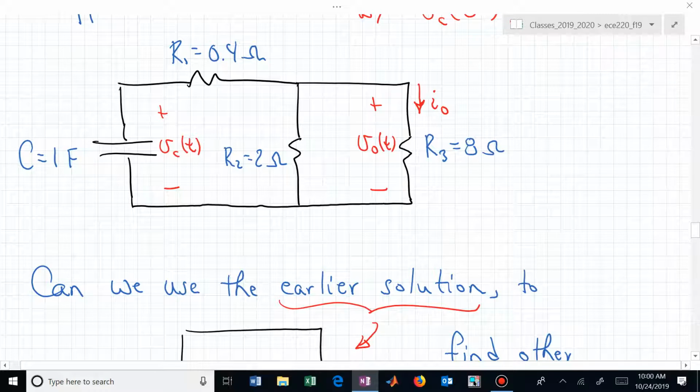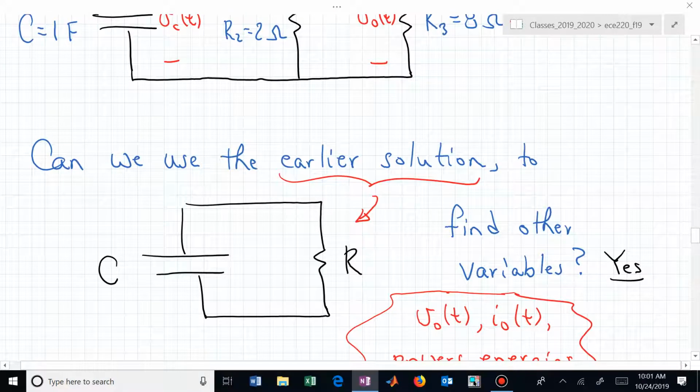Your terminals of the capacitor, or let's say terminal A and terminal B, you want to go, okay, what's the Thevenin resistance between those two terminals? What's the resistance between terminals A, B, where A and B are on either side of the capacitor, and now we're looking into that circuit from the left to the right, and we want to know what's the effective resistance seen by that capacitor. If we can find that, then we can just write the circuit as this and analyze it with that effective resistor. And we can then find the voltage of that capacitor.